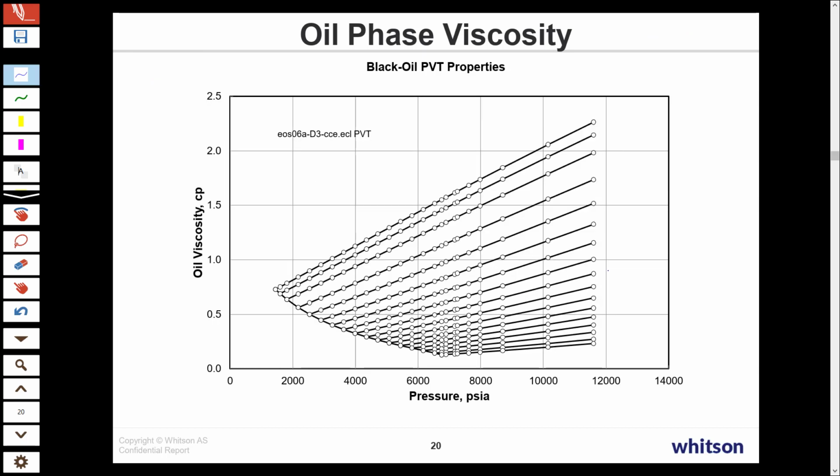Now we're going to put all of the undersaturated properties and saturated viscosities together. Along this line here, these are the saturated viscosities. For any new oil, this oil has more gas in solution than this oil. And of course, the original oil is somewhere out here, maybe this one here. For the oil with the most gas in solution, there's much less viscosity increase with pressure.